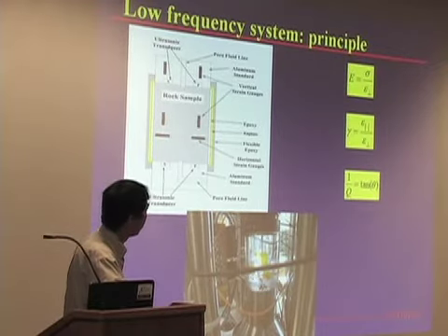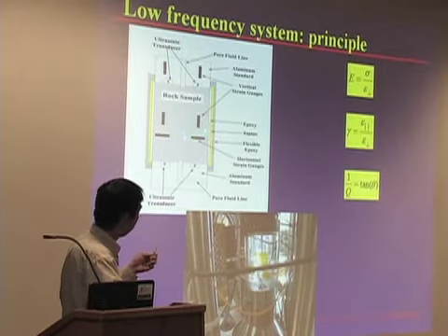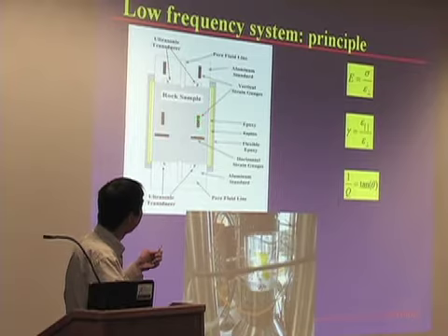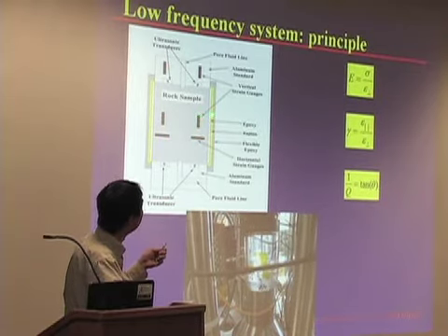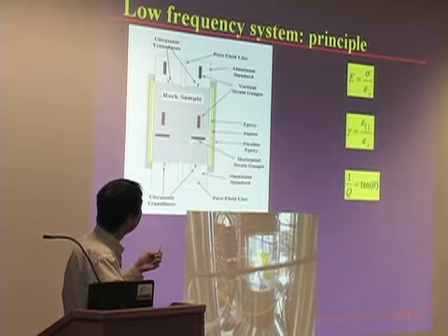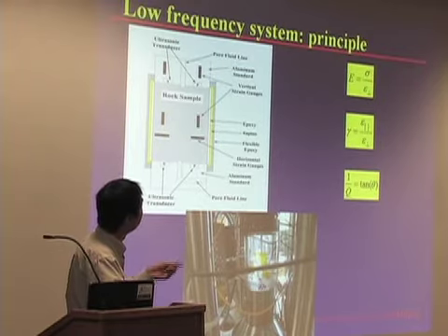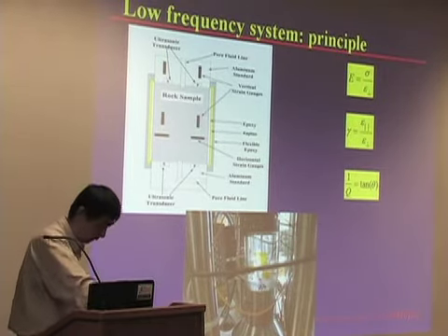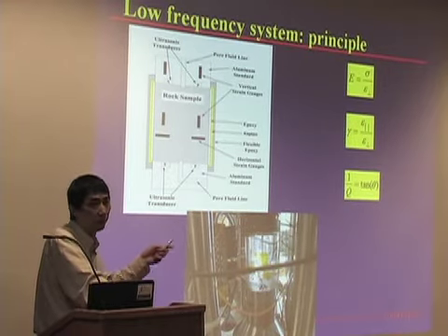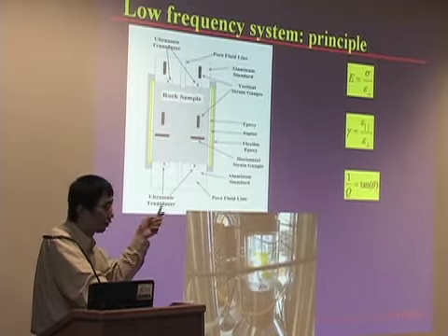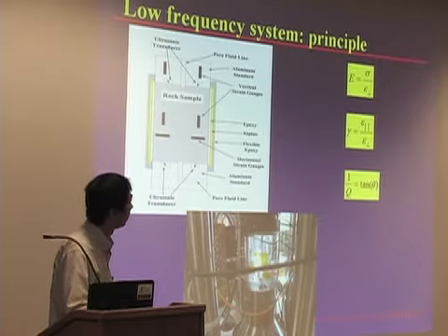Then a little bit of detail about how to get the elastic modulus and attenuation. Normally we have to put multiple strain gauges in both the vertical direction and the horizontal direction. The vertical one will measure the Young's modulus, and the horizontal one, along with the vertical one, will measure the Poisson ratio. Then, assuming it is an isotropic material, we can get all other elastic moduli like bulk modulus and shear modulus.